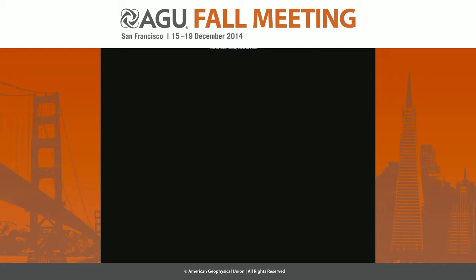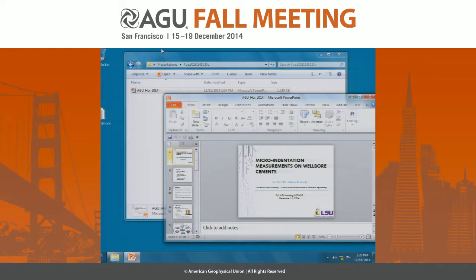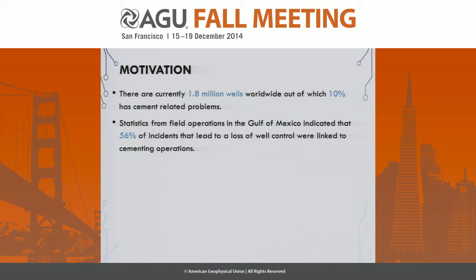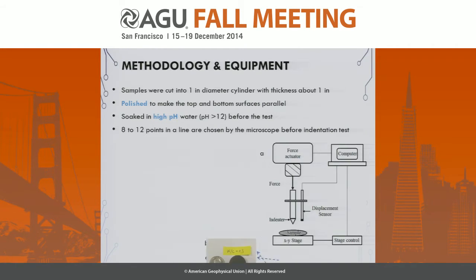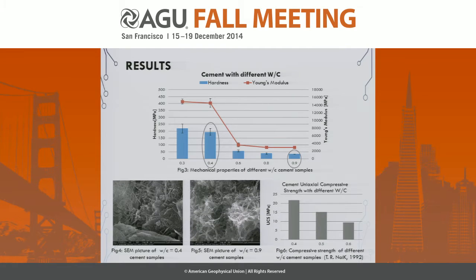Well, there is a minimum amount of compressive strength. I think it's 5 megapascals, as you can see on my slides right here. With a 0.6 water cement ratio, the compressive strength is about the minimum amount required. Also, the recommended, I remember, is 12 megapascals at least.